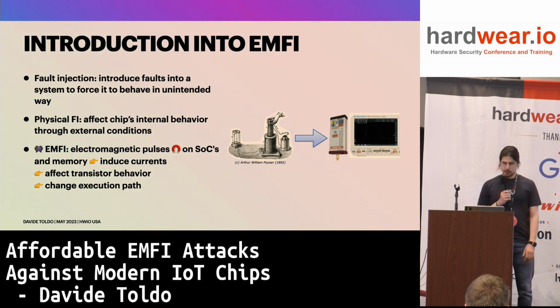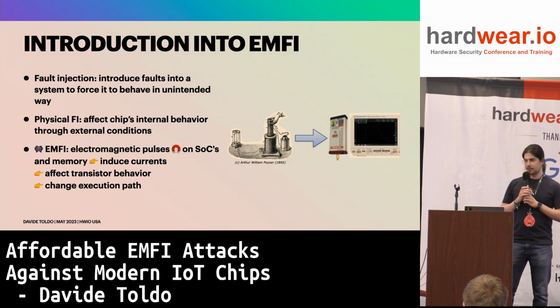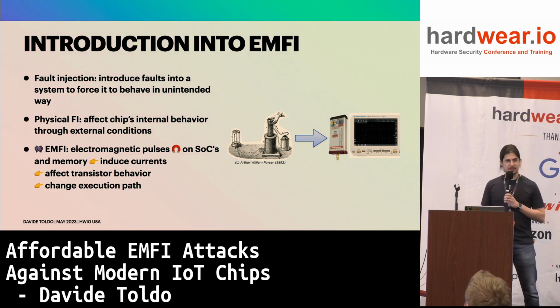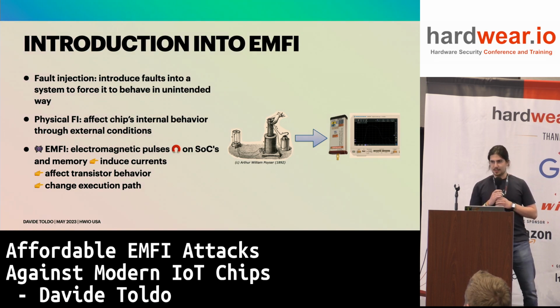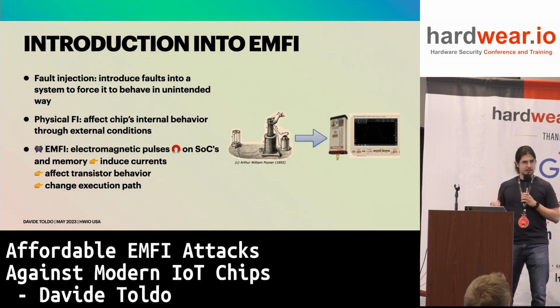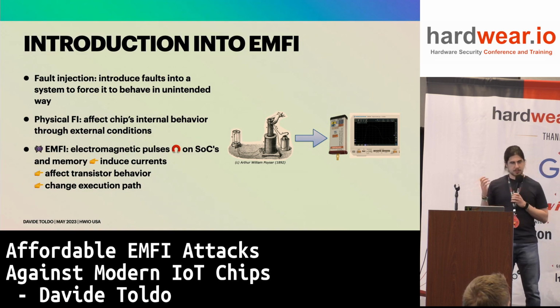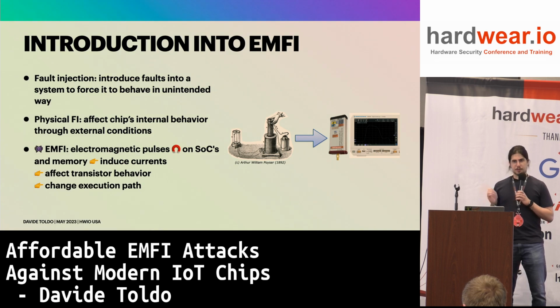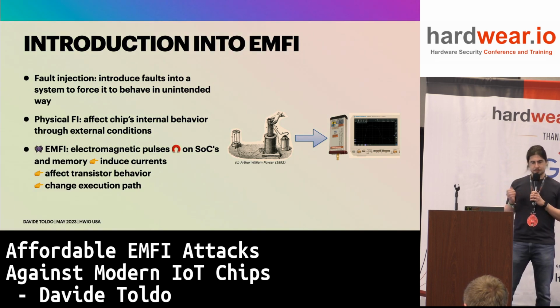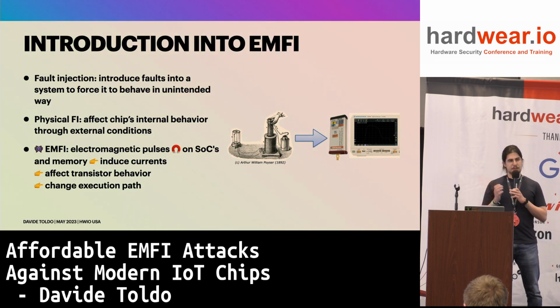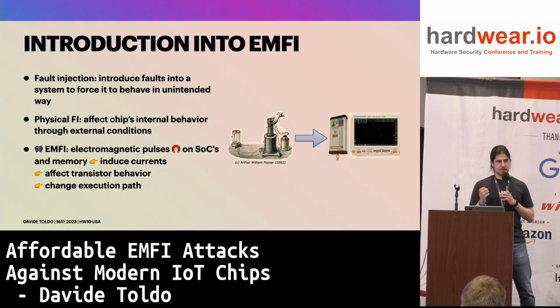EMFI in particular leverages electromagnetic pulses that are placed exactly on top of an SoC. And I think I'm the first one quoting a 19th century textbook at this conference. But the principle is not that special. You have Faraday's laws, and magnetic fields that move across each other and induce currents.